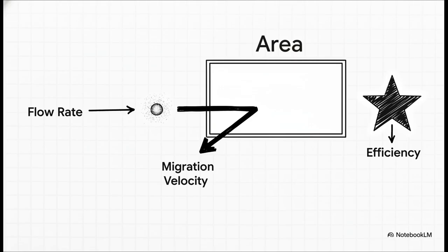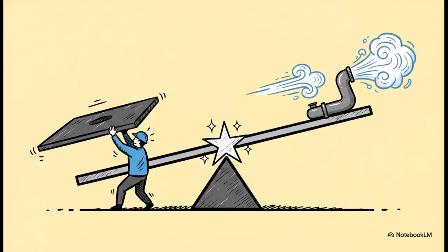Now, to make this math work, the equation operates on a few key assumptions. Gas velocity is assumed uniform, particles are fully charged, and we completely neglect the repulsion effect between the particles themselves. Okay, let's actually solve an example together, right now, to really see the engineering trade-offs mathematically. Let's imagine a small factory stack. The particles move toward our plates at a migration velocity, VPM, of 0.1 meters per second. We have built a collection area, AC, of 100 square meters, and the factory is pushing gas through at a flow rate, Q, of 10 cubic meters per second.